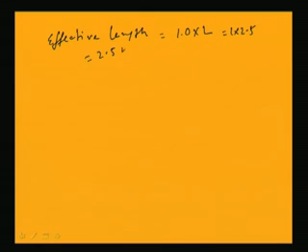Now, we will go for the design of the member, whether the member is able to carry that much load or not, that we have to see. So, what we will see? First we will see effective length. Here effective length will be 1.0 into L. So, that will be 1 into 2.5, so 2.5 meter. So, lambda max will be L by r minimum.